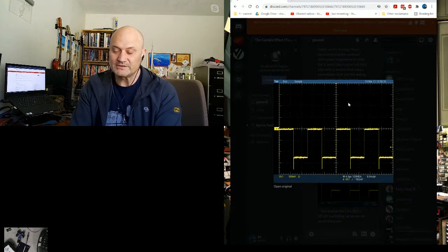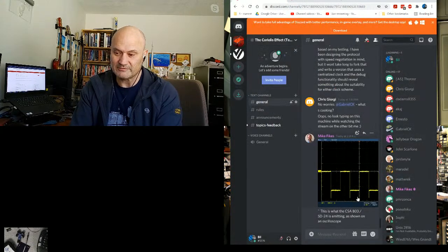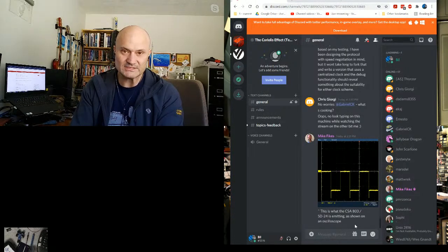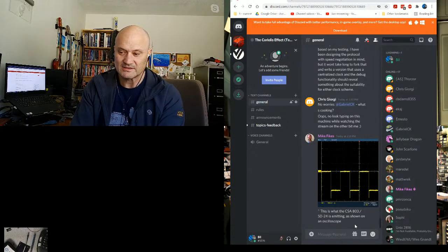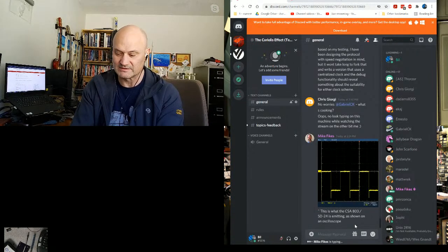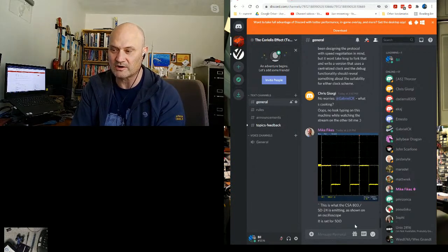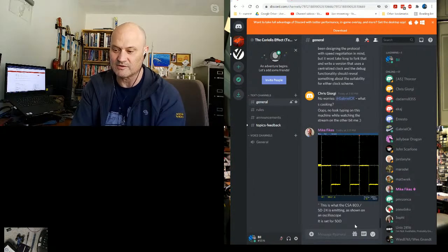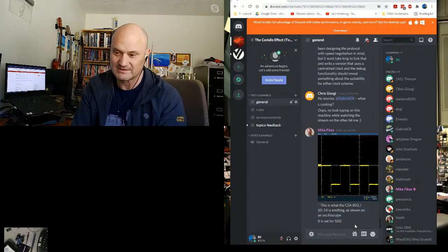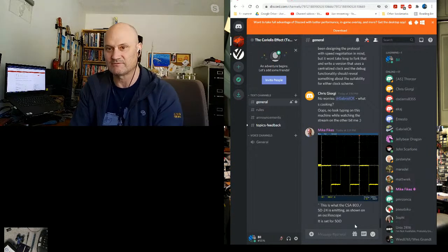Yeah, so all you need to do basic time domain reflectometry is a good square wave or pulse signal source, some good connections into the device under test, and the right kinds of terminations, and a fairly good high bandwidth oscilloscope will do the trick. And everything else, so here's a question for you for people who want to do it that way. I noticed on the CSA that you're doing this too. You've got the y-axis or vertical divisions in millivolts. So how do you know what's impedance from that?